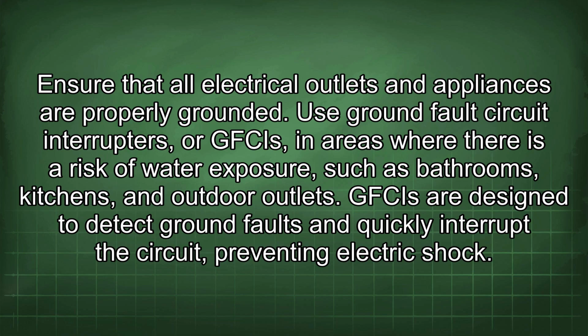Use ground fault circuit interrupters, or GFCIs, in areas where there is a risk of water exposure, such as bathrooms, kitchens, and outdoor outlets. GFCIs are designed to detect ground faults and quickly interrupt the circuit, preventing electric shock.